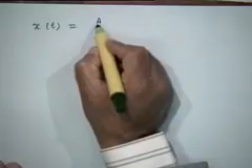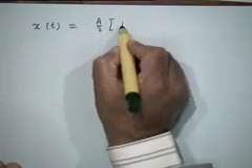That quadrature representation. So obviously the SSB signal had that representation. The VSB signal also will have that representation. The only things that will change are the actual values of x sub I and x sub Q, the actual nature of the in-phase and quadrature phase components. So we will certainly be able to see that this signal that we have generated will have this form.